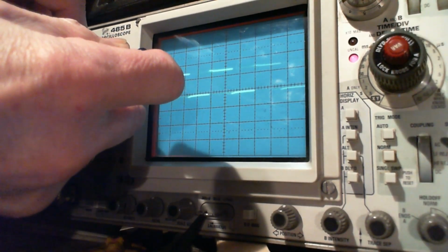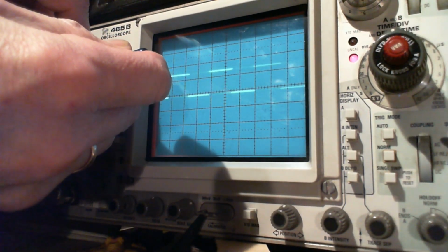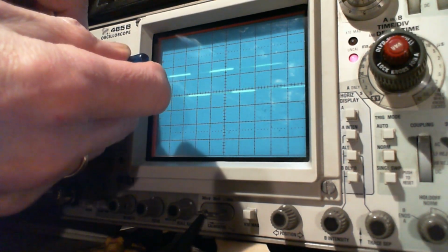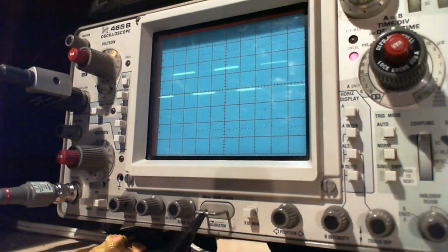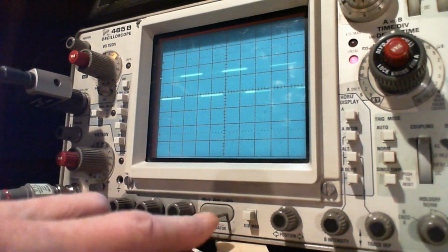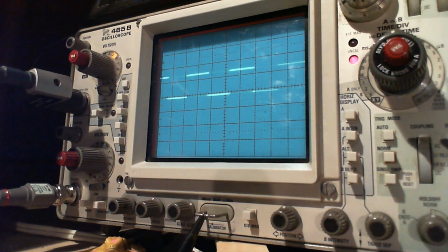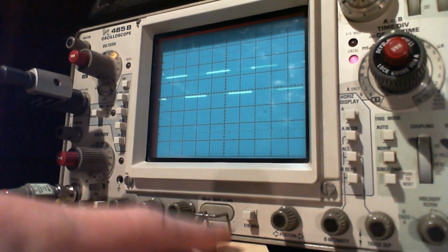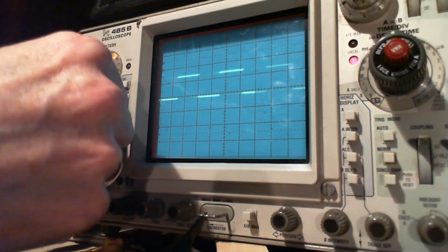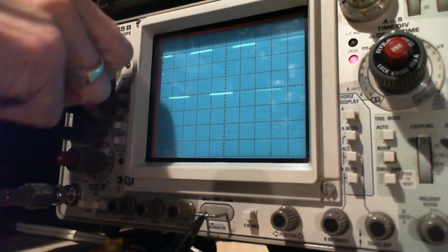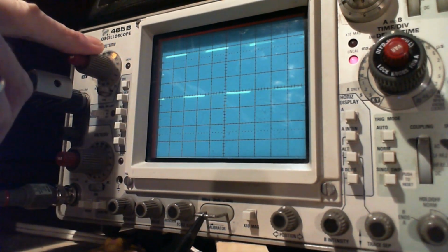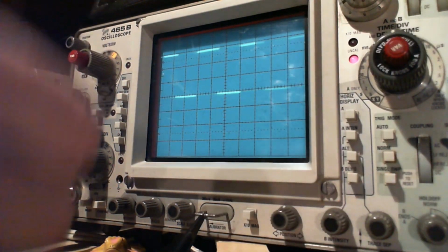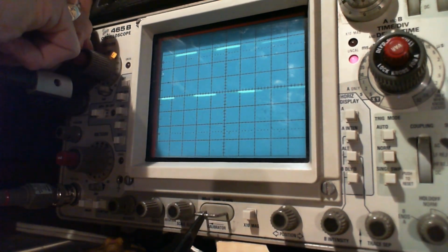So this actually isn't going to have an impact on the low frequency measurements that I'm using this for, but there we are. Now that looks nice and square to me. So what I believe I can do now is take this test lead and put it on the square wave coming out of the other unit. Now this is supposed to be 300 millivolts. Let's just make a quick check of that. We're on DC here. If I put this to 0.1, that should be 3 squares, 3 divisions. So let me just move this right on a line.